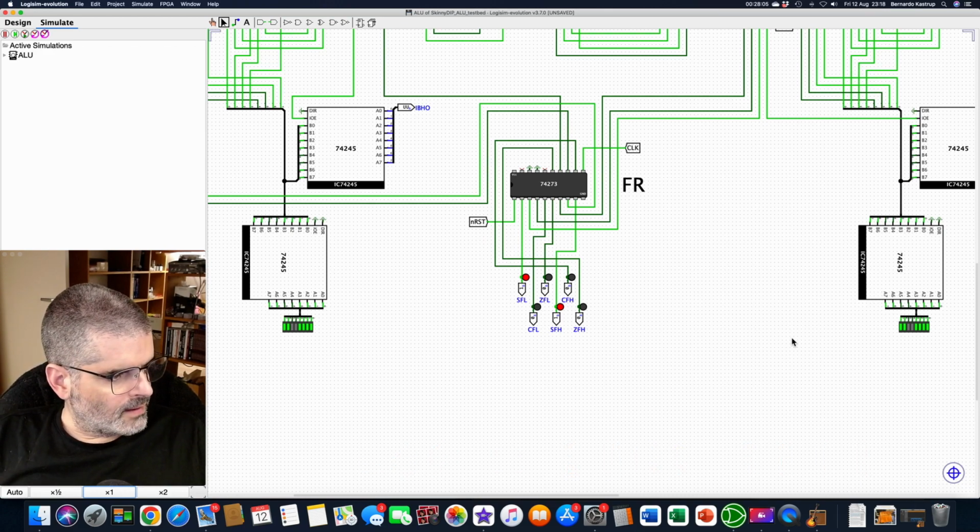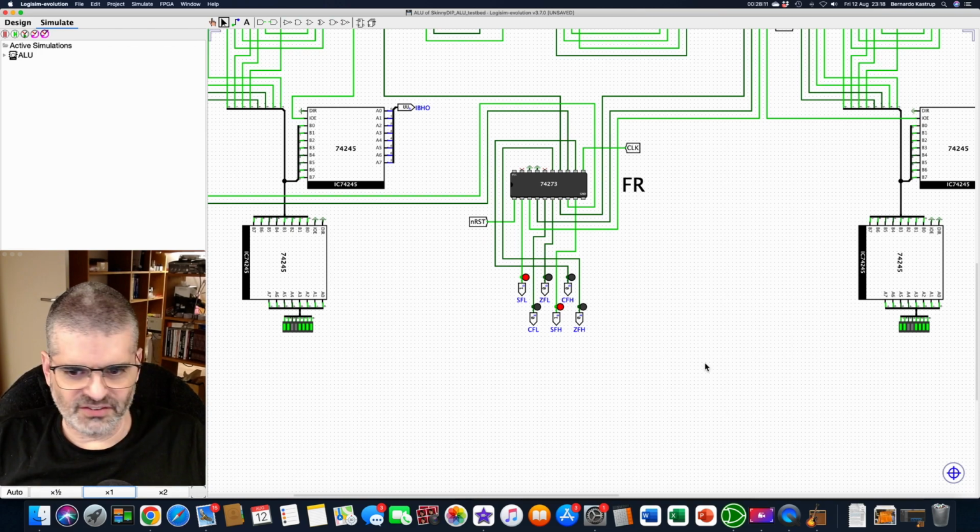Correct. And now this is 2's complement notation, so the sign flag is relevant now. Let's see, sign flag low is active, correct. Low has a negative number, and sign flag high is active, correct. It's also a negative number on the high part of the ALU, both are minus 49. They are not zero, so the zero flags are low, there's no carry.